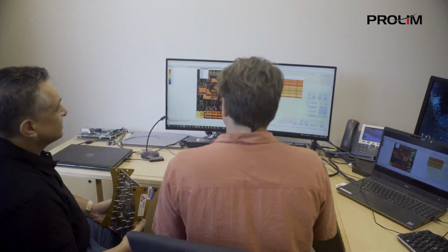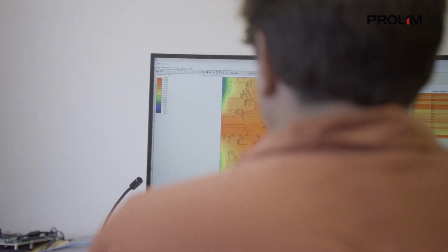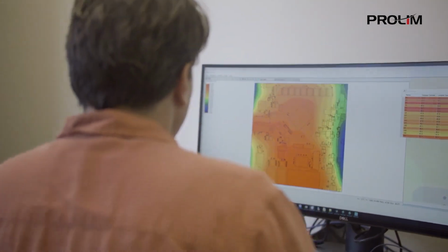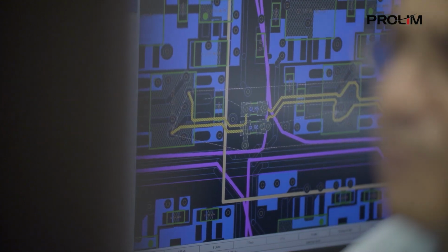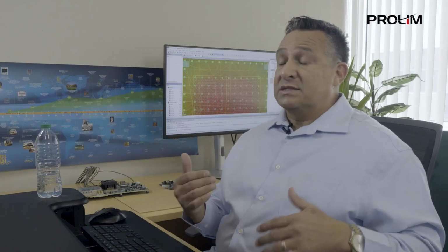People use a standard approach when they could be utilizing these advanced capabilities or advanced design features that are out there. When it comes to designing, a lot of times the roadblock is that it requires a SME, or subject matter expert, or inefficient processes reduce the opportunity to implement HDI. So the best practice for HDI and advanced design is utilizing the opportunity for rigid flex methodology within our toolsets, which allows a more efficient way to define a board outline, as well as the stackups and regional constraints that you would have.